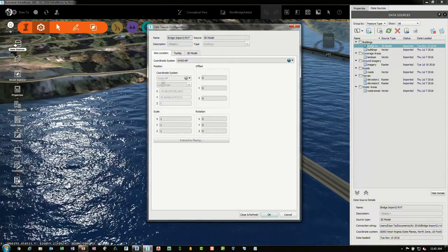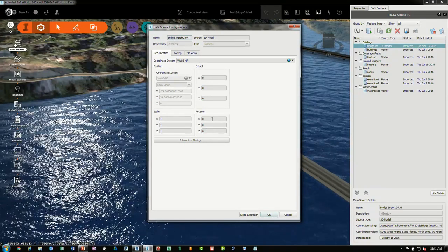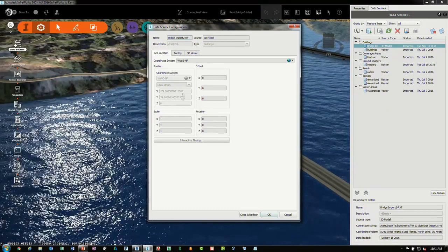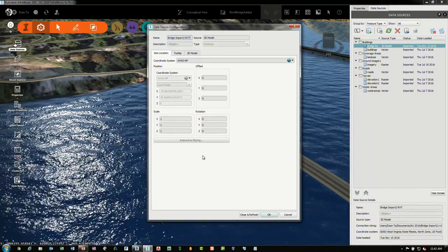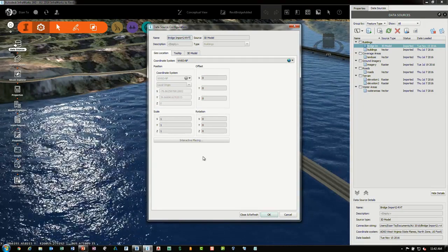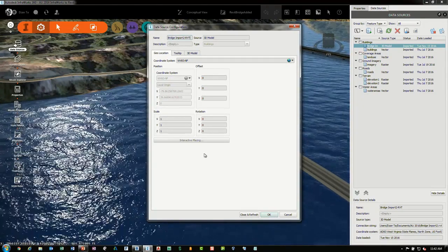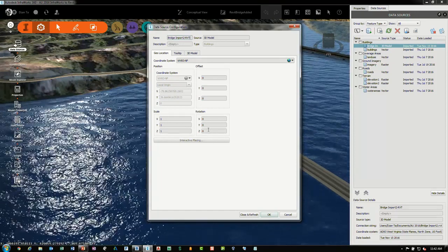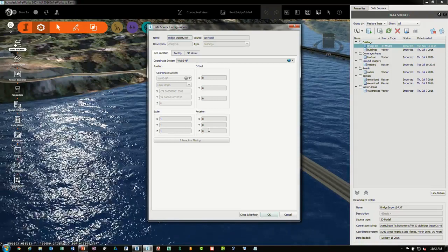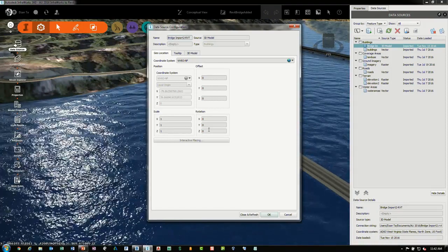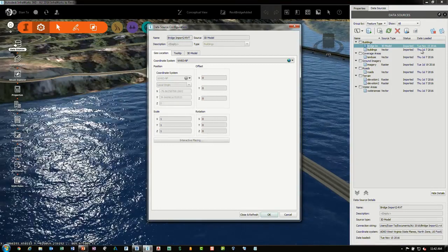So by default, when you bring the Revit file into InfraWorks, this information will not be assigned properly. And you'll have to make the necessary adjustments. And then it'll say imported. And like I said, if you pull the handout and go through the step-by-steps, because in the handout I have it actually written out step-by-step what to do, even down to the point of the coordinate system, then you'll understand why it says imported versus configured. Okay.